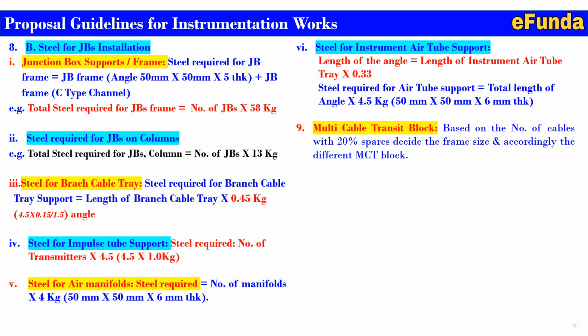One has to estimate, based on the frame size, the insert block type quantity based on the number of cables entering the control room. The spare block is a consideration for future cables, in case they are added later based on modification, advancement or optimization of the process where some additional instrument installation is required. Those cables will enter through the MCTs into the control room.